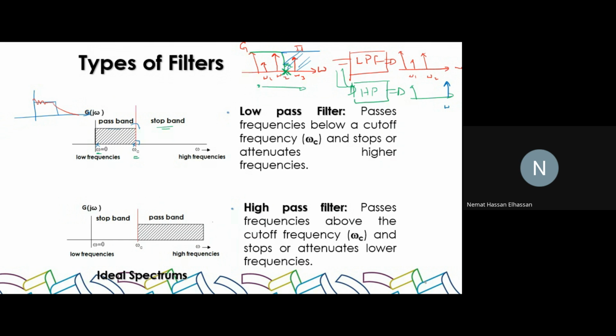Now, as a designer, usually your goal is to get as close as possible to the ideal, which means you want to minimize this fluctuation, the ripple effect. You want to enhance this transition to make it a little bit sharper, right? However, solutions to make the gain stable tend to make the transition slower.